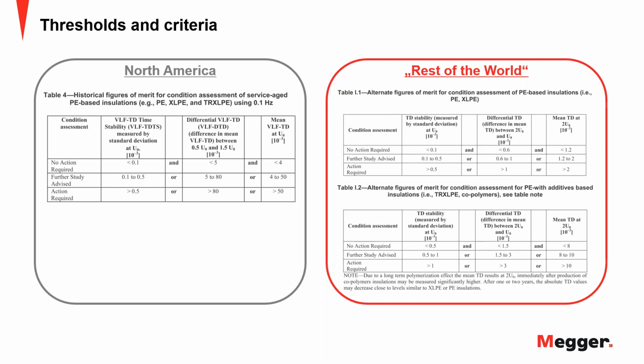All right. Moving on, our next question is to Henning. Henning, does it make sense to do global assessments on brand new circuits before putting them into service? Well, like Robert was saying, tan delta is a typical method to do global assessment in terms of aging condition of the cable. So I answered that a little bit before when we talked about commissioning versus service aged cables.